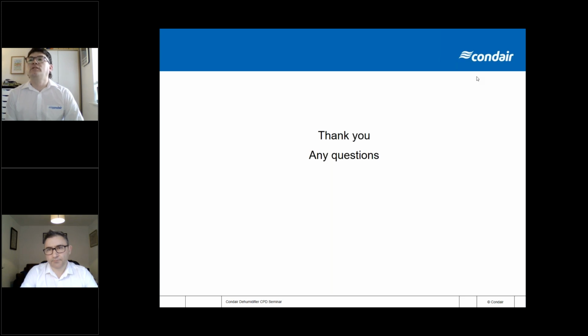Brilliant, Dave, thank you. And then last question, last but not least, another great question. Is there a certain air leakage the room has to have for the room to work efficiently? That's an interesting question. Air leakage we would consider as part of the load, because if air leaks, then we've got an infiltration rate, and the infiltration rate will be added to our load calculation. So we would want to know what leakage rate you would expect, and we would add that into the duty calc of the dehumidifier. So not especially critical, but we do need to know what you would expect the infiltration rate to be if you're leaking air.